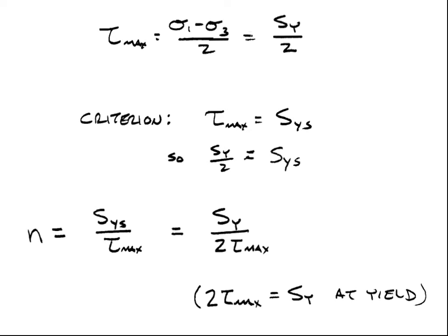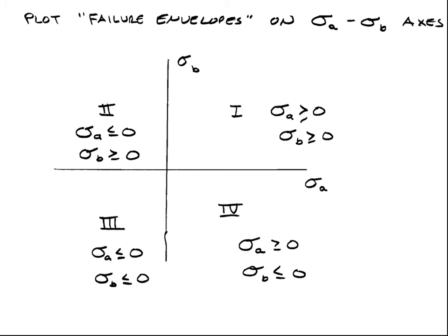It's a tongue twister sometimes. An important result here is that you don't have to know the yield strength in shear to apply this criterion. A lot of times when you look up the material properties, you only see the yield strength in tension, but you compare that to 2 times the shear stress for this criterion.